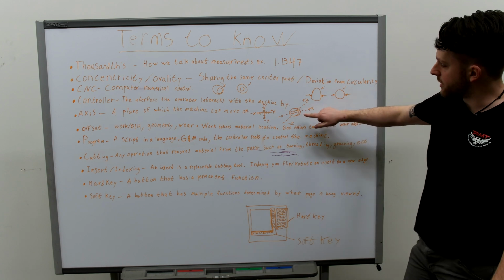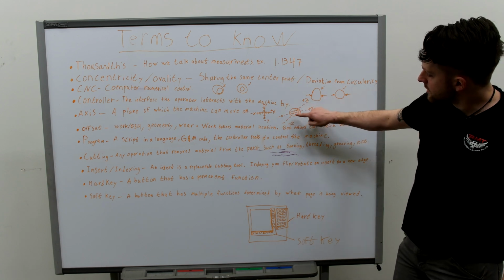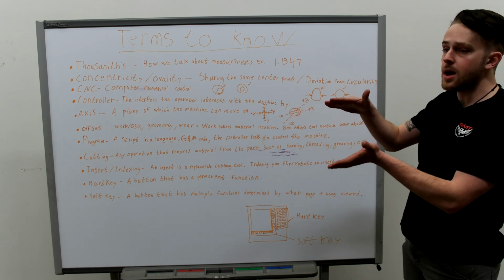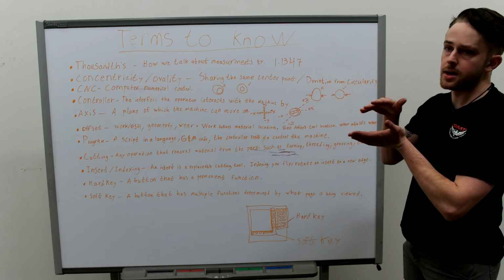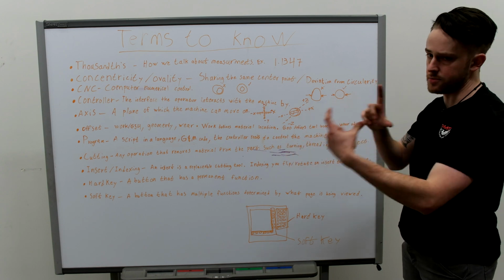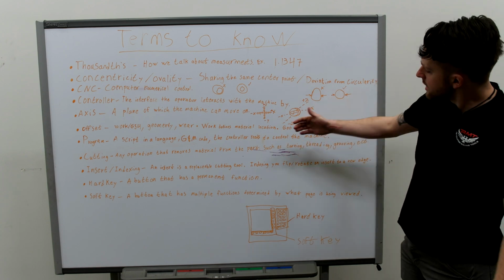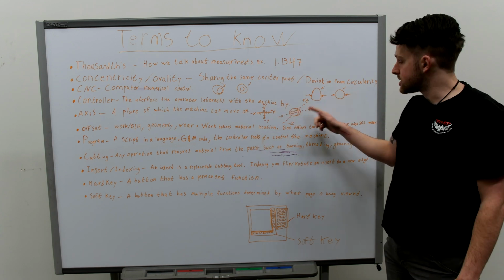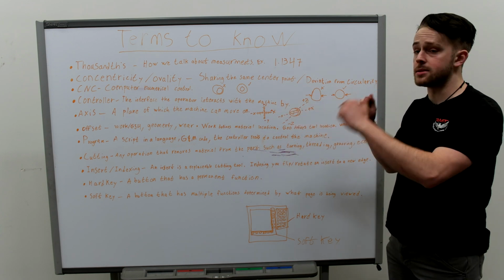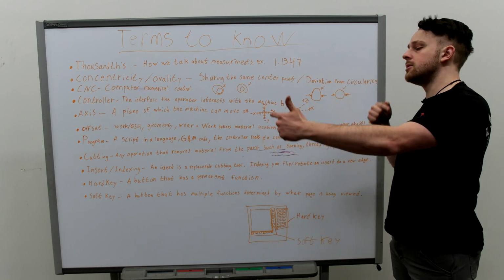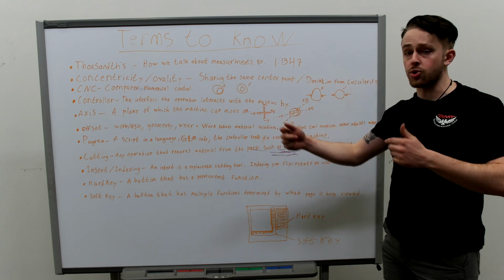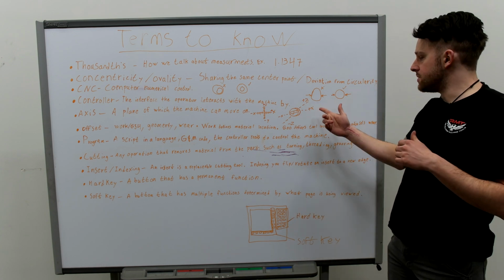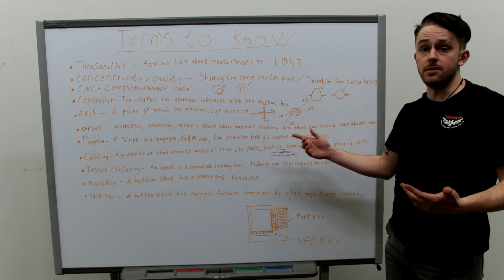So my example over here is this is our spindle. The solid lines intersecting the spindle are the X movement. It's the actual plate that moves in X. So it's not always right and left for the X, which side is positive and which side is negative, because it determines where the spindle is oriented, right? If it's oriented upside down from what we typically think, then our X positive and X negative would be inversed.